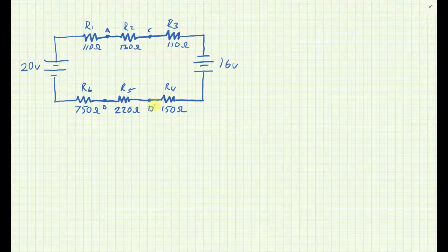Now particularly I'm interested in what the diode is going to see, because the capacitor will charge to whatever is available to it, and if that value changes, it will discharge to, again, whatever is available to it. Now that diode, once it sees the conditions of the circuit, if the conditions are met in which it will bias in one way or the other, its voltage will be held to that value. So the voltage between C and D will be determined by that diode.